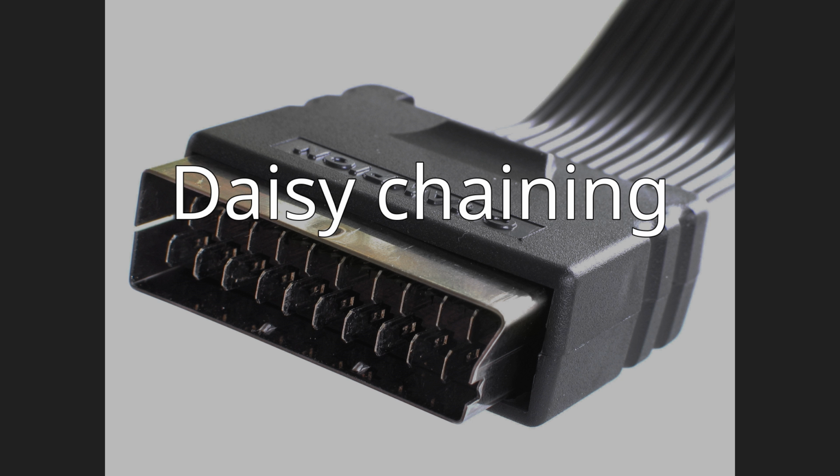Daisy chaining. Scart is bidirectional regarding standard composite video and analog audio. A TV will typically send the antenna audio and video signals to the Scart sockets all the time and watch for return signals to display and reproduce them. This allows transparent set-top boxes without any tuner, which just hook and pre-process the TV signals. This feature is used for analog pay TV like Canal Plus and was used for decoding teletext.